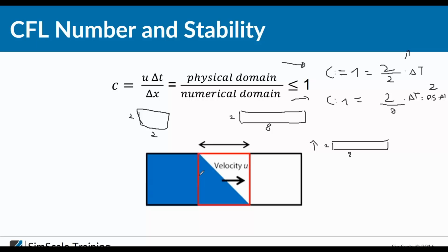But Christian, we had a customer who wanted to simulate some so-called fireboxes, and he just simulated air. If you're not really interested so much in the combustion itself, you can replace the combustion with a good heat boundary condition. And we also cannot do condensation. That's a limitation of the volume of fluid method, it's only working for non-mixing phases.